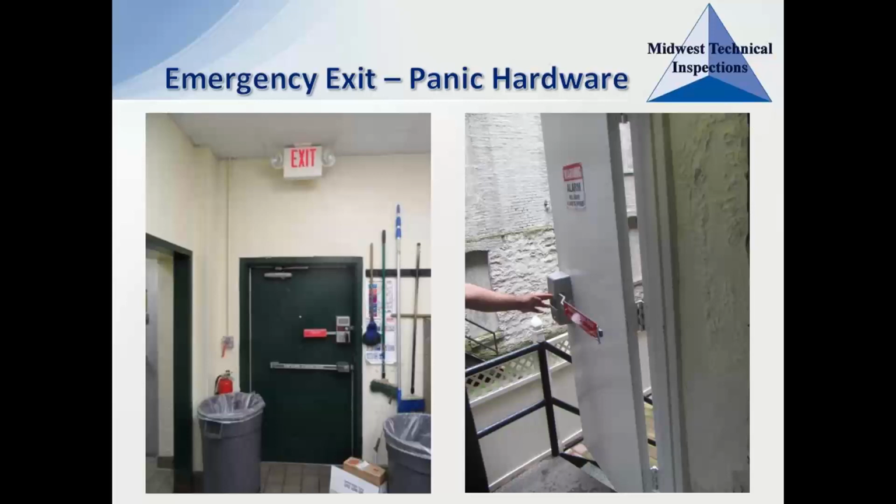So they had an exception where they were allowed to open their door inward because they don't have a high volume of people inside of the building, and because of that extenuating circumstance with the outward swing. So they had a special exclusion where they were allowed to have their exterior doors, their exit doors open inward. But generally speaking, you want your exit doors to open outwards. And you wouldn't be able to have a place of assembly, like a bar or a restaurant or a club or anything like that, where there's a lot of people and have the doors open inwards. So that's just not going to work.